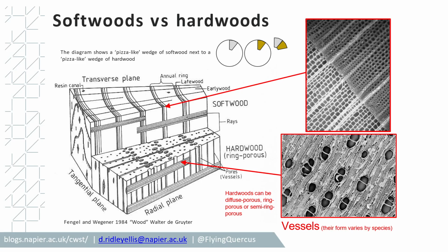Hardwoods are different, so it's not just because of how the trees reproduce, but that is the defining factor. But you'll find hardwoods do look different under a microscope to softwoods. The general theory is pretty much the same though, with that moisture, sap movement, vertically and horizontally.